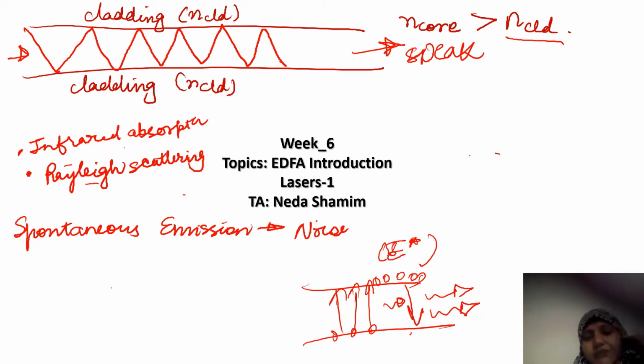And here what do we see? Erbium doped fiber amplifier, that is, we have this fiber amplifier, and erbium has a relatively longer lifetime of the excited state. So it can stay in the excited state, that is, population inversion will be maintained for a longer time until a signal photon comes.